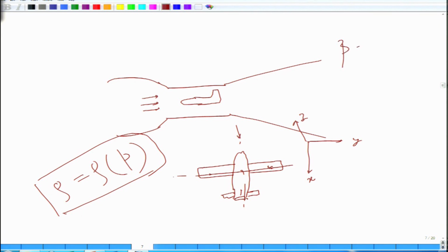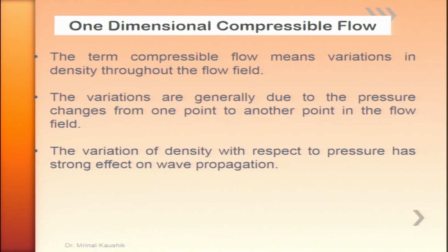be defined as, let's say, beta is defined as minus 1 by volume and then dV by dp, that is a fractional change in the volume with respect to pressure, such that when you apply a compressive pressure, the change in volume, that is the volume shrinks, and hence we say this is a compressibility reflecting that you are applying the compressive forces. And from this point we said that whenever the change in density is negligibly small or it is almost constant, that is nothing but your incompressible flow.